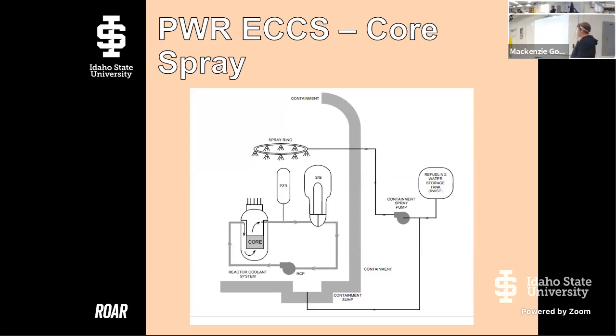And here's a picture of it, right? You have your core here and your containment building, and you're gonna spray cool water in, and then when you get that moisture that now condenses down at the bottom, you have a sump, and you'll pull that moisture out so that you don't have it heating up and creating steam and creating pressure again, right? And so you prevent that problem of creating an issue with your steam.